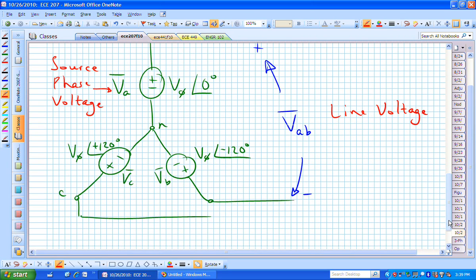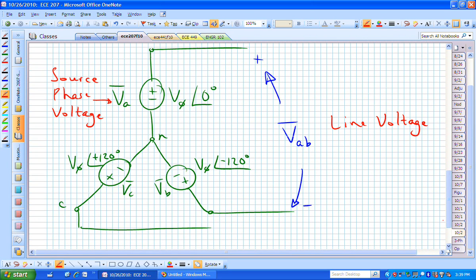The question was, and I think this is rephrasing your question: you're saying, if I visually do a KVL around that with an air gap including VAB, that will give me VAB, and it looks like one is subtracted from the other, and they both have the same magnitude, so why isn't that 0? It's because they aren't quite aligned in angle.